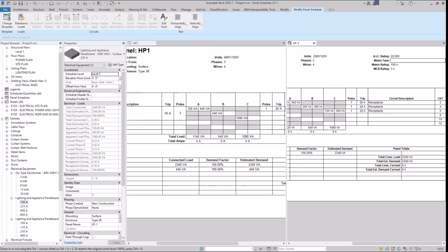When you have that many amps flowing through there, 20,000, 65,000, whatever, there's a lot of magnetic force and a lot of ability for that arc to jump free air. When the circuit breaker opens, there's only so much space between each chunk of metal, and if there's enough amps there, it can still arc across that free air space. And if you don't have it rated properly, either your panel board would be crushed due to the magnetic forces, or even though the circuit breaker is physically open, current is still passing through it because of the arc.